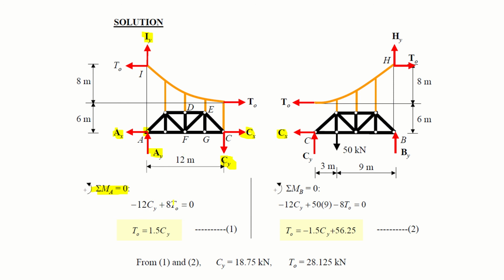And the second thing, we are left with the T naught, T naught over here and T naught over here. So this T naught is making movement in the clockwise direction and its perpendicular distance is 6, right? However, this T naught is making movement anti-clockwise and its perpendicular distance is 14. So 14 minus 6 is equal to 8. The resultant is 8 in the anti-clockwise direction into T naught. Got it? This is equal to 0,